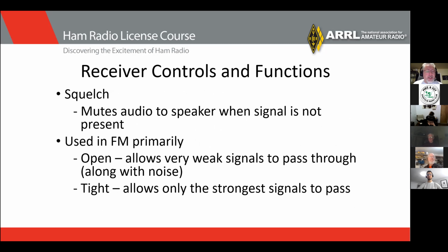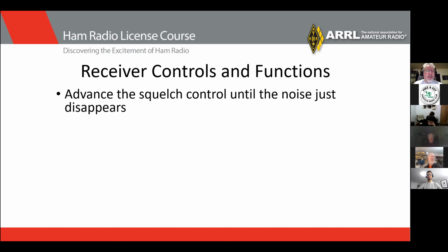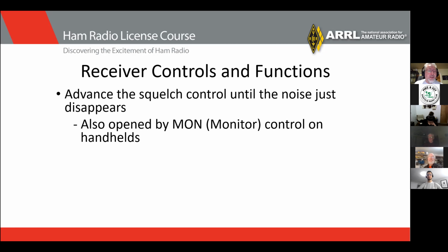And if you tighten the squelch, that allows only the strongest signals to pass. Advance the squelch control until the noise just barely disappears. Also open by a monitor or MON control on handhelds.